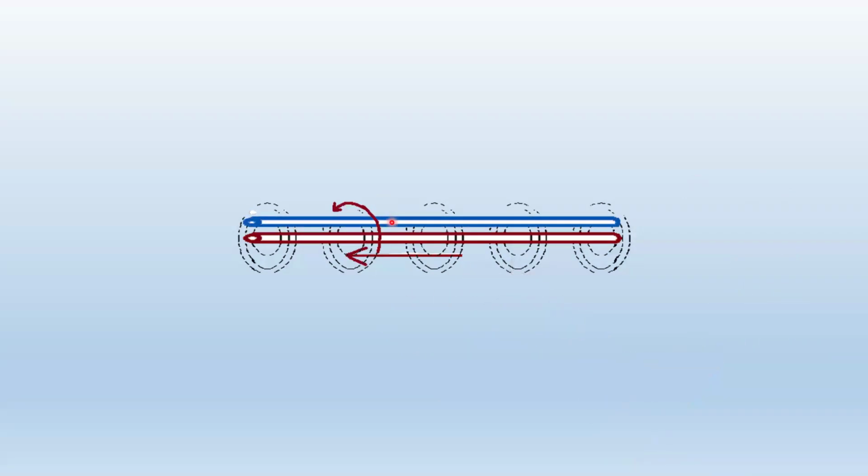If you put another conductor in close proximity to that active conductor, and this could be an inactive conductor, which means it's not connected to any power supply, it could be connected to just a resistor, and that's it, this wire is not powered, but by means of induction, if that wire finds itself within close proximity so that the magnetic field around it is strong enough, it is going to induce an electric current in this other conductor.